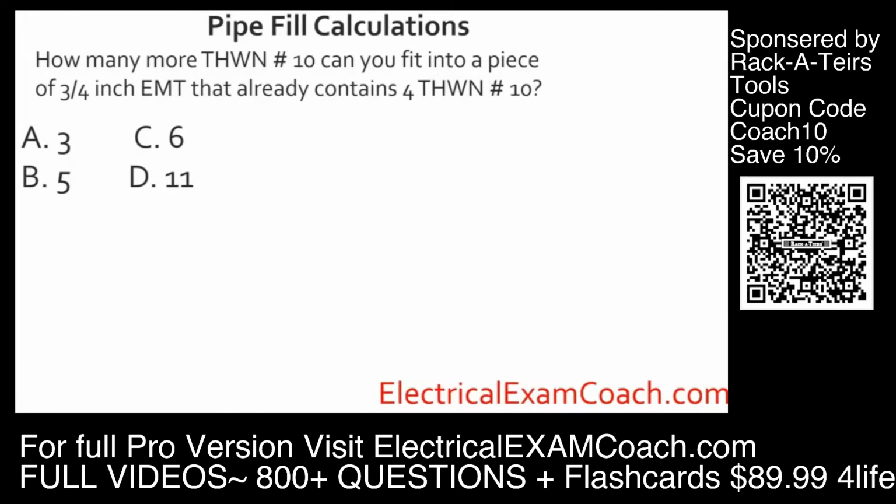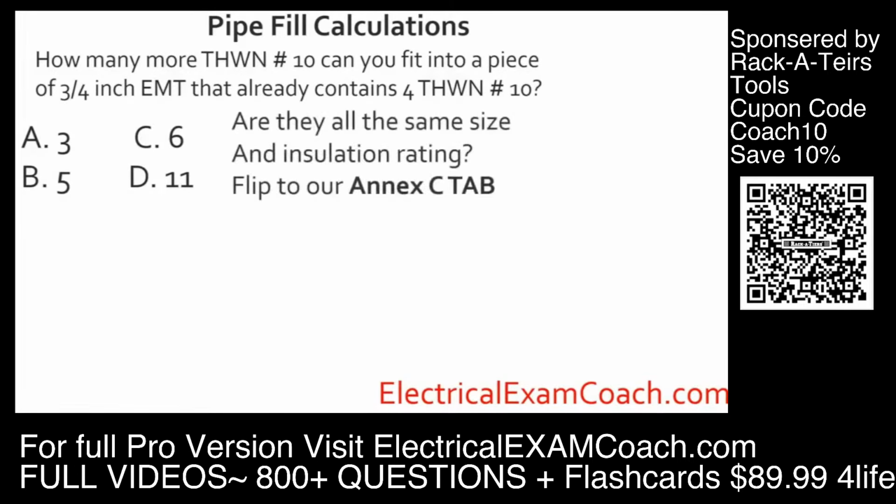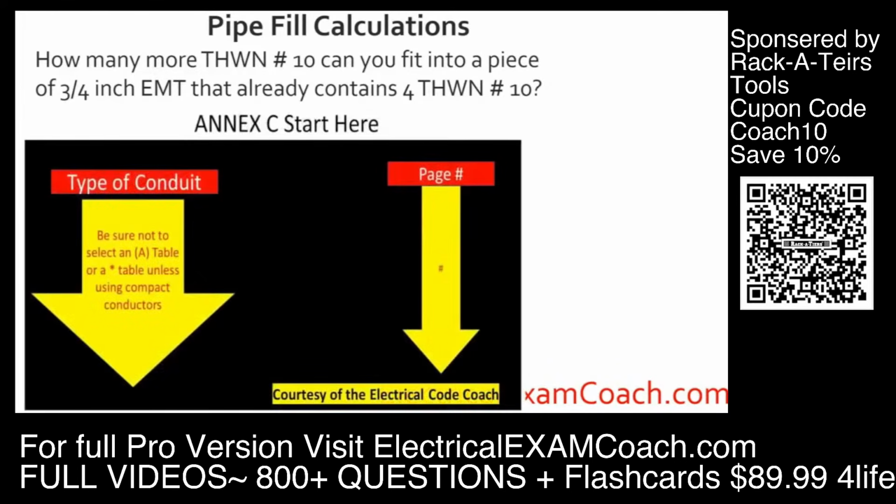How many more THWN number 10 can you fit into a piece of 3/4 inch EMT that already contains 4 THWN number 10s? The first thing we're going to ask ourselves, are they all of the same type and insulation? They sure are. So let's head to Annex C. When we get there, we're going to start on the left-hand side and find our type of conduit, being sure not to select an A version of the table.